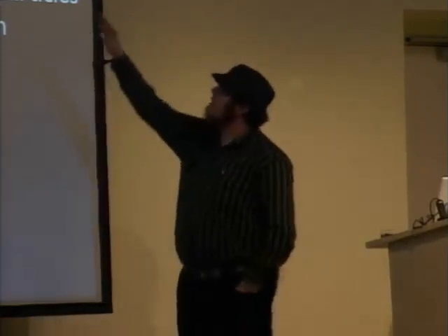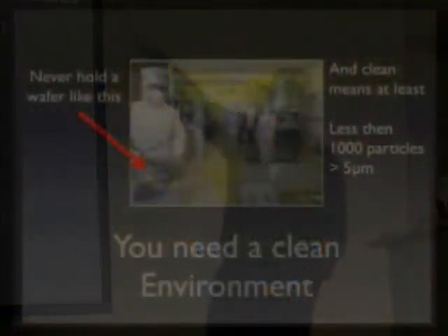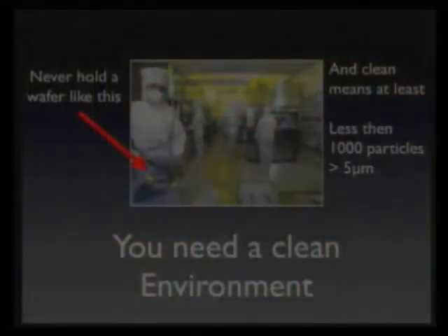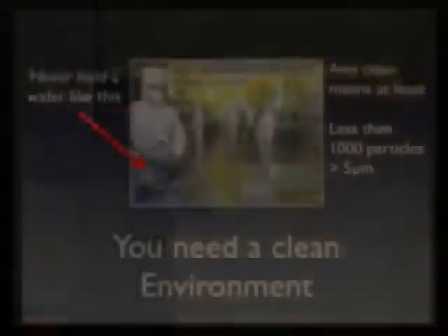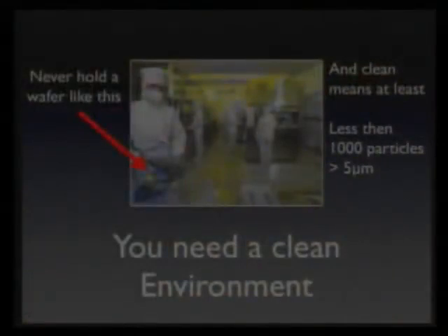Honestly, when you're in a small clean room and you have 3 people there, try to be there at 9, because after 12 o'clock you won't get any good results anymore because of particle impact, and people are moving, so you get turbulences. It's really bad. So what they're doing is laminar flow from the top to the bottom. All the tiles you see on top are basically nets where they blow air through and suck it away here on the bottom. And also all the tables have holes so that the particles can settle down and get sucked away.